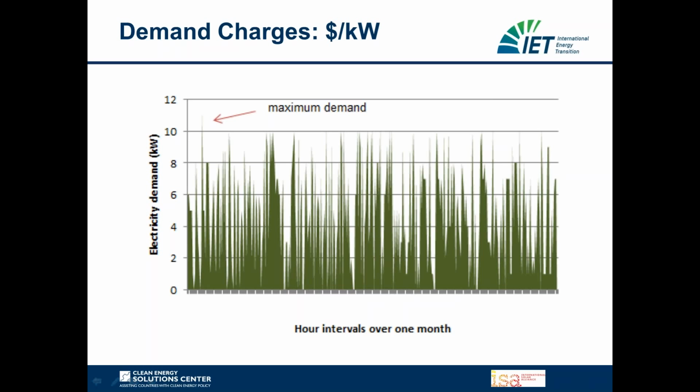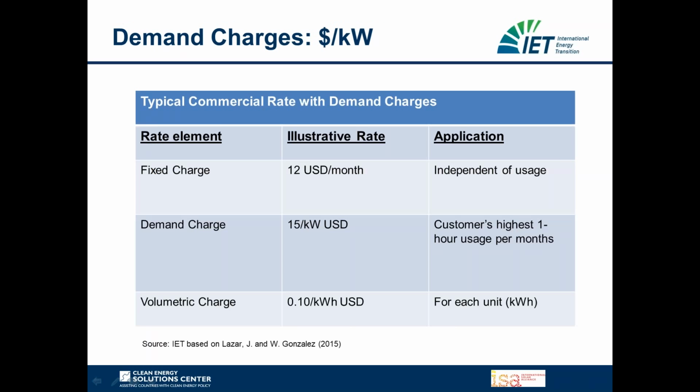So you look at the entire year, you look where the maximum demand actually happened, and you take this hour as the calculation factor that you will use to calculate the demand charge. For instance, here's a typical commercial rate with demand charges based on a study from Lazar from 2015.